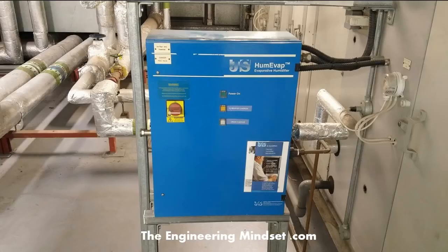Another way to do it would be through something like this, which is an evaporative humidifier. You can go for a steam system as well, so there are many ways you can add moisture to the air, and it depends on whether the environment is critical or not. It used to be in many offices, put in there to control the static in the air. But more and more this is being switched off. It's very energy intensive, and there are various guidelines to tell you where and when you can and can't do that, so I would recommend you research that before switching these off.